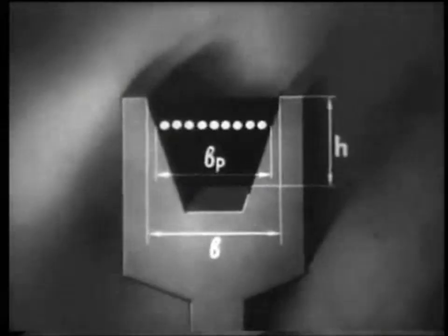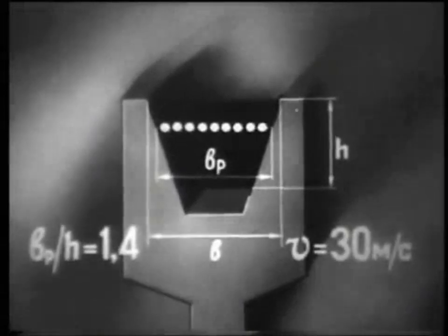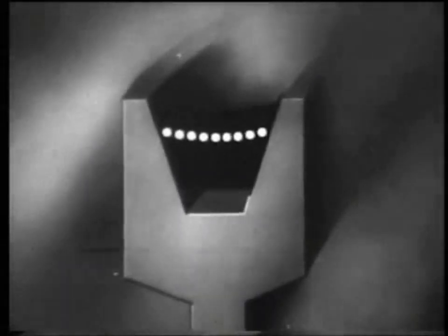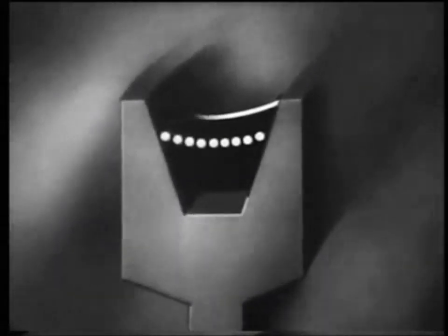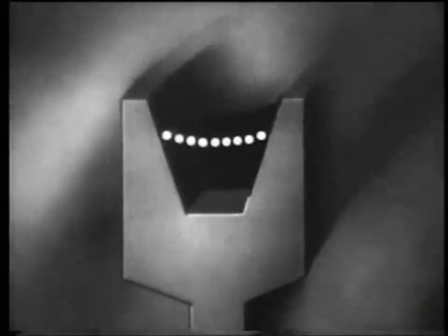In general, mechanical engineering mainly uses belts of normal cross-section. Their disadvantage is that when stretched, due to the deflection of the belt in the groove and the eccentricity of the application of friction forces, the load is distributed unevenly across the width of the cord.